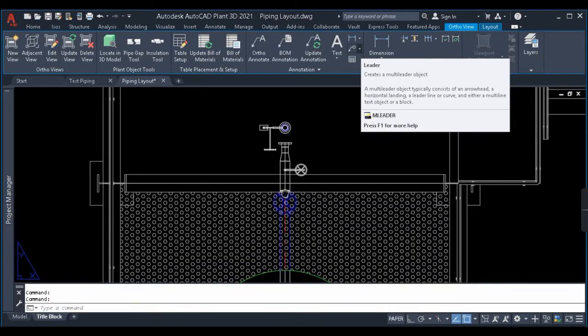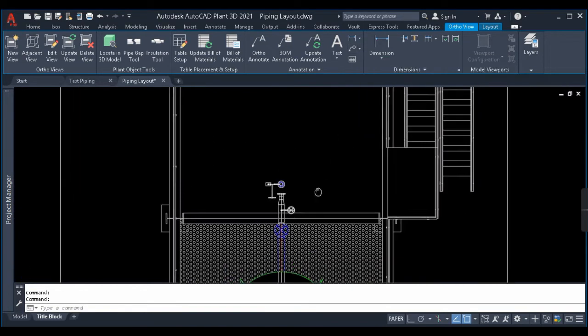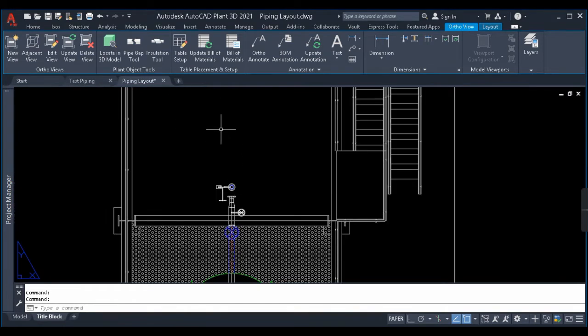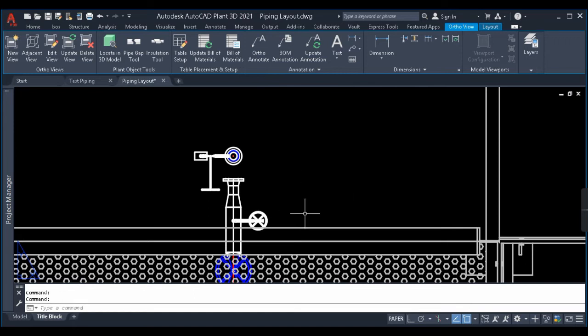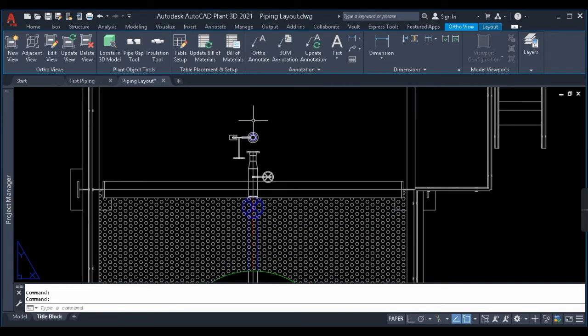So now our drawing has been generated. In hidden line piping you can see here whatever piping is coming below this solid plate has been displayed, but we also have a pump here, which is an equipment, which has not been displayed because we had selected the hidden line piping option. In hidden line piping, as I told you, only the pipes which are there in this cube will be displayed, not the equipment. So I hope you understood this option now.